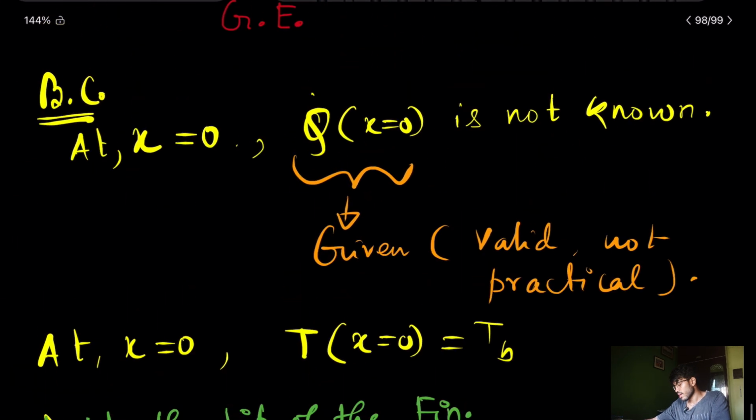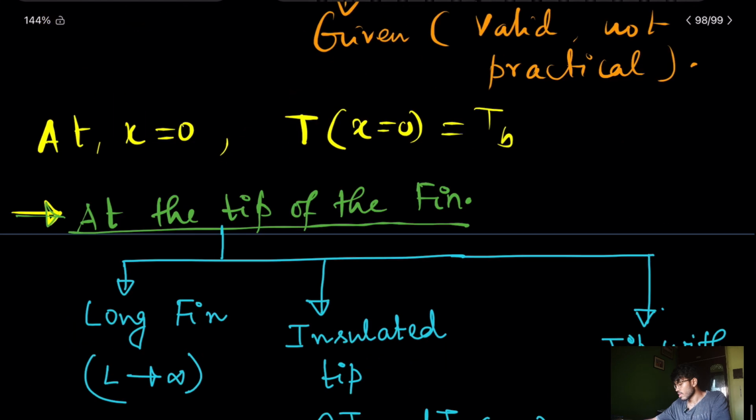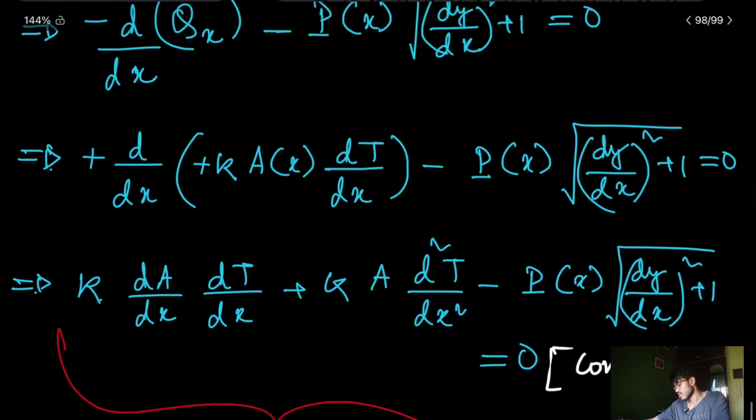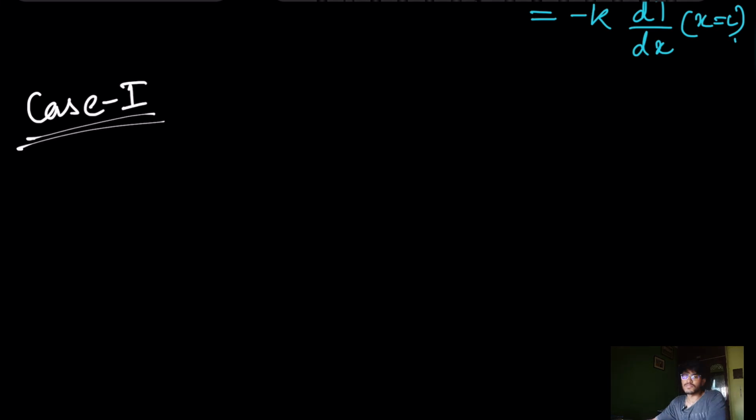So now we have got the boundary condition and the governing equation. Okay. So let us solve the fin for the case that you have already studied in your B.Tech. So case 1. Okay. So this fin will not be a very large chapter to complete. Okay. We will take two cases, this constant cross section and one varying cross section.